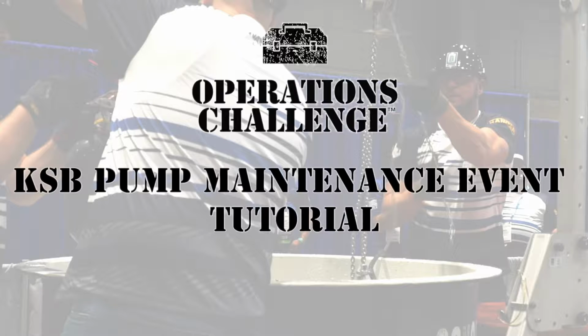These wipes have led to countless numbers of sanitary sewer overflows and additional maintenance and overtime by wastewater workers to keep our systems up and running. These flushable wipes are resistant, flexible, and not designed to be quickly disintegrated in a sanitary sewer system. In fact, they tend to stretch and braid themselves together until they ultimately cause a system failure or a problem.